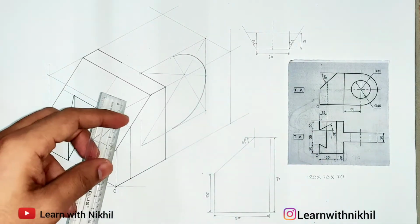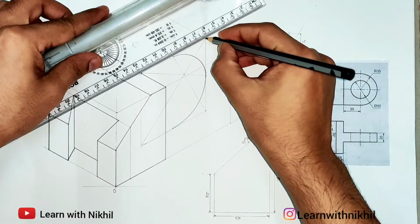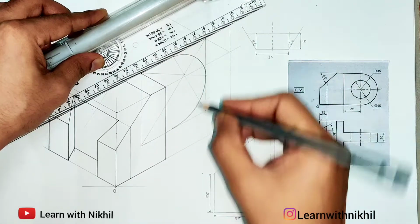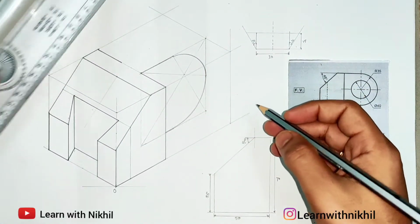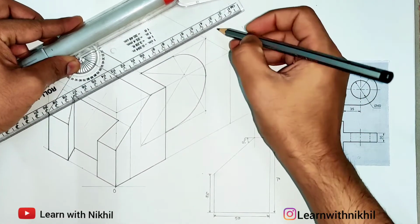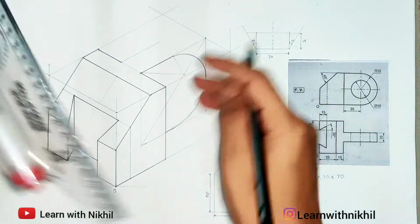So this is the semicircular part. Other lines you can draw dark. So draw this part dark, bottom till this part only will be dark, as the other part is hidden behind, so you need not draw it dark. Now the thickness given is 20 millimeter, so from here I'll draw a light line.